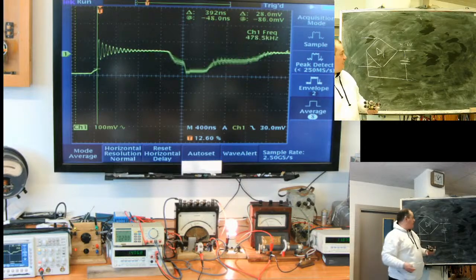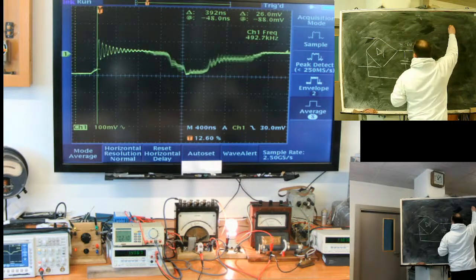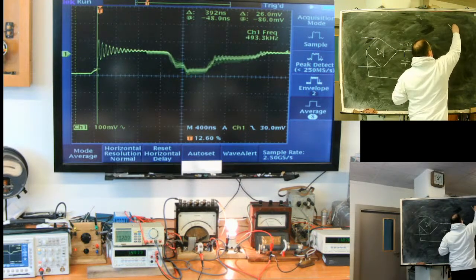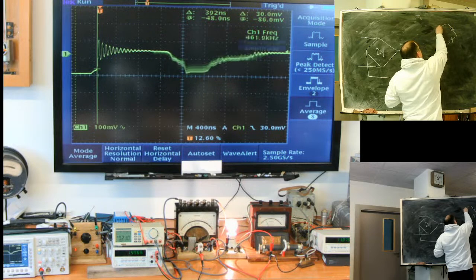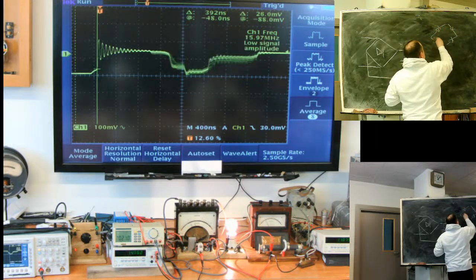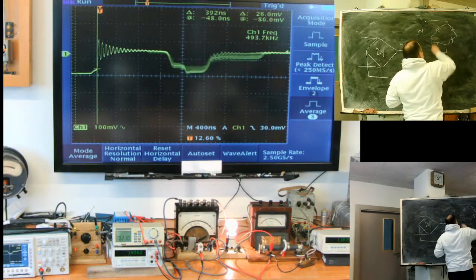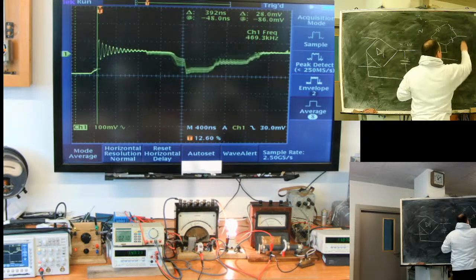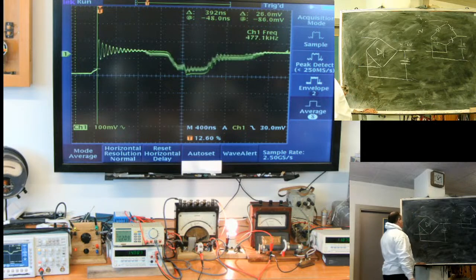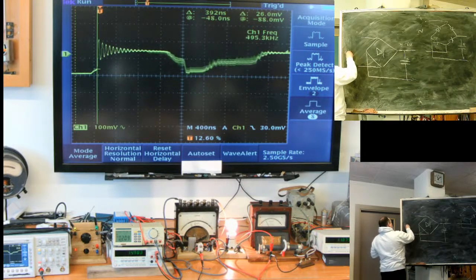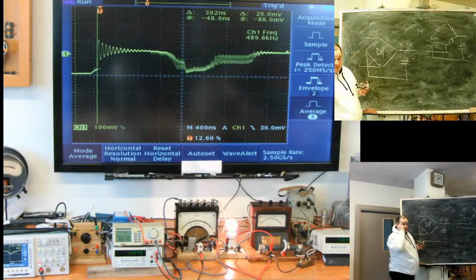No, it's integrated here. One second, I have drawn it like this, so it will be one diode, second, and the number 4 just indicates that each side has a diode. Yeah, it's a common symbol for a bridge. Here we have 230 volts AC. At the output we will have 300 volts DC.